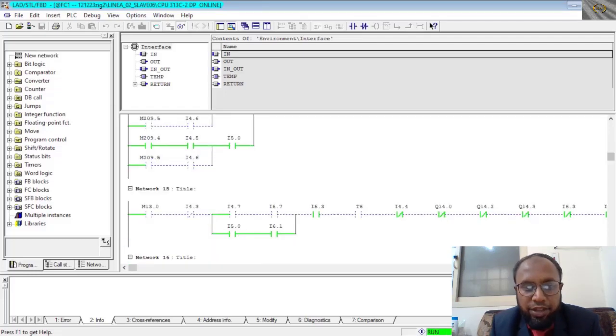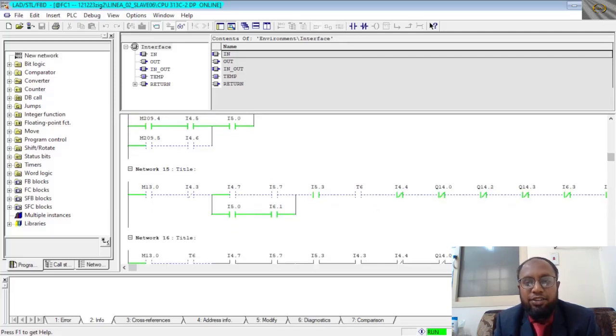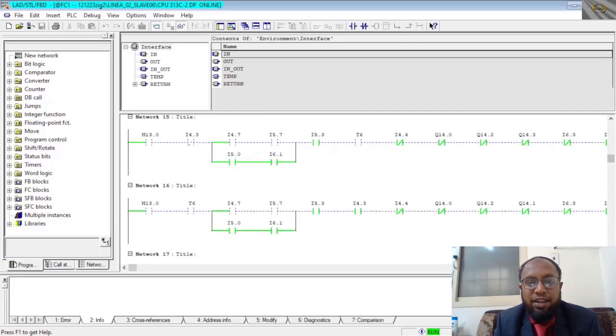Then finally, we see our problem is one of the limit switches. That limit switch was stuck, so we turned it on and off. Then T6 is working properly. Now finally our problem is fully solved and our jig runs and moves slowly.